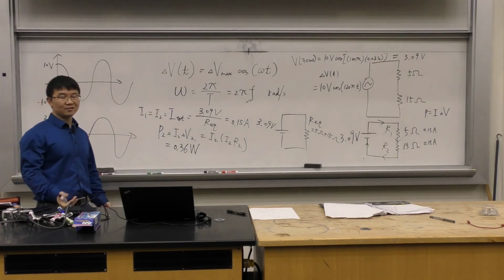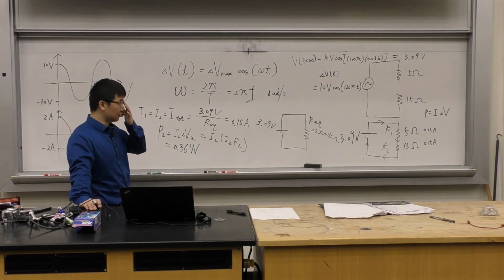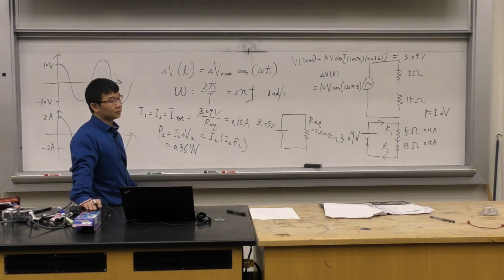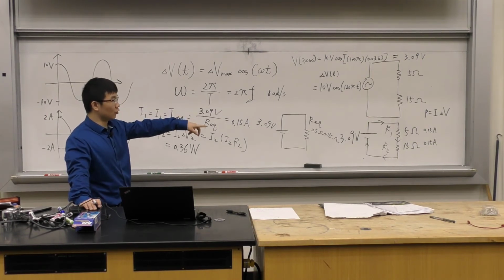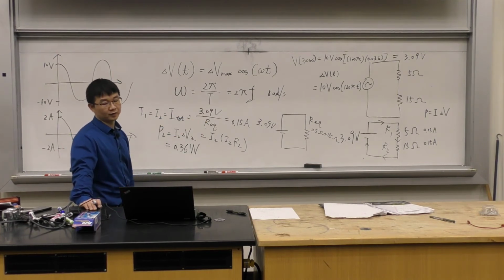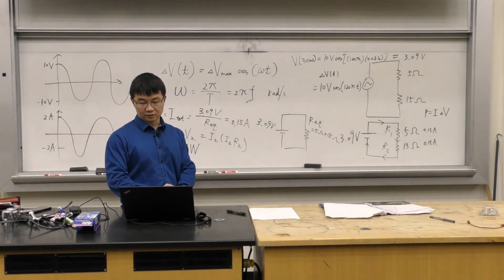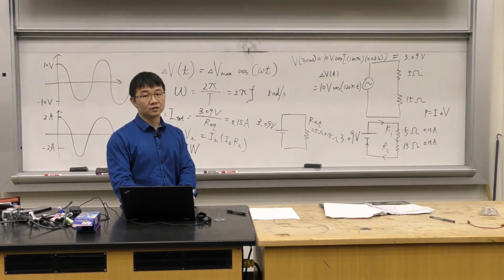Okay? So there's nothing special if you connect a resistor, or even many resistors, to an AC circuit, right? If you want to find some instantaneous value, the problem is always going to tell you a time. So you just find the voltage at that time, replace the source with a battery with that voltage, and then just solve the DC circuit, right? Nothing special, okay? So I don't even need to remember any theory for resistors connected to an AC source. It's pretty much like what we do in a DC circuit.